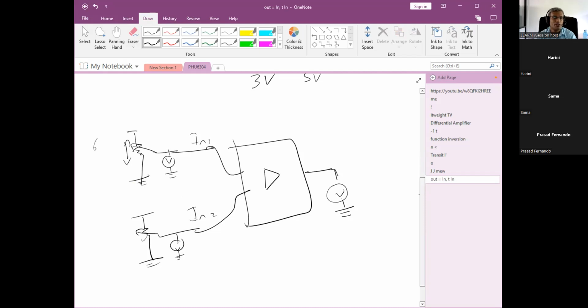For example, if you want to have 6 and say -2, you should have minus voltage, okay? Then you configure it until you get 6 volts in here, -2 volts in here. And what will be the value you are getting here? Four volts. The summing amplifier can get negative values. There's no problem. You get 4 volts. So in a way, it is doing the addition.